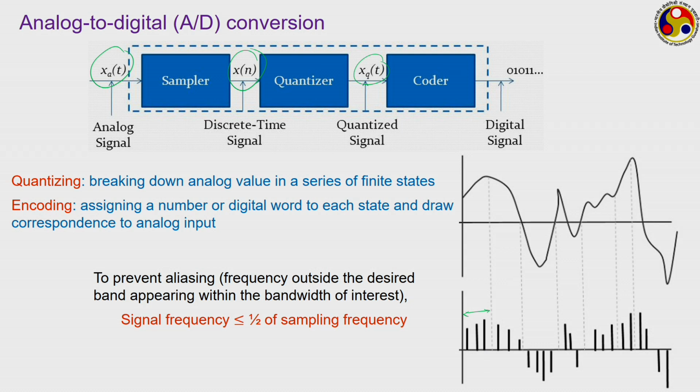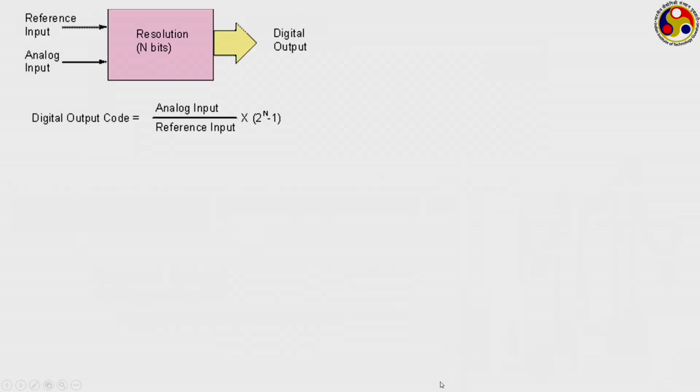In this example there are 3, so if this time interval is 1 second, then your sampling frequency is 3. The higher the sampling frequency, the better; your instrument will be able to give a much better representation of the actual analog input. To the lowest limit it should be at least twice the actual signal frequency. This particular rule is called the Nyquist rule.